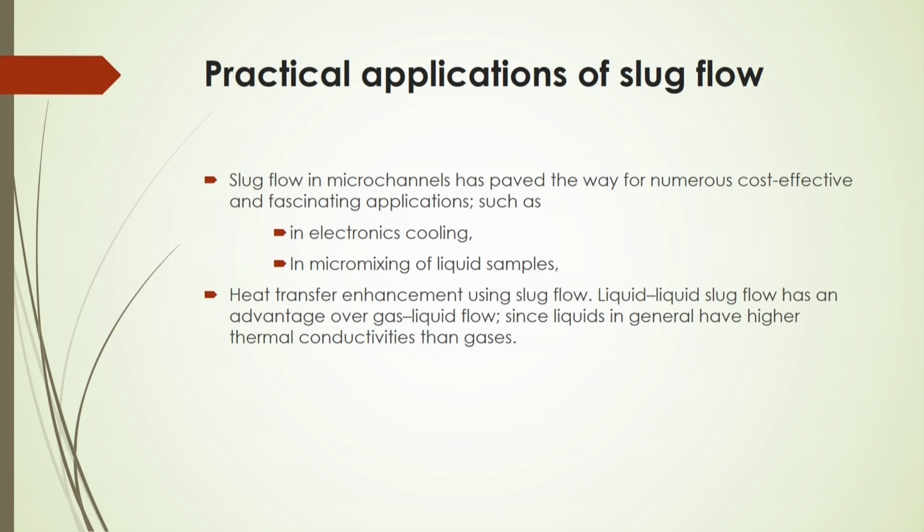Now, practical applications of other flow patterns, like slug flow, if you are considering that. Nowadays the slug flow in micro channels has paved the way for numerous cost-effective and fascinating applications, such as in electronics cooling, in micro mixing of fluid samples, even micro reactors. Sometimes slug flows are used there to have more efficient reaction and better yield of the reactions.